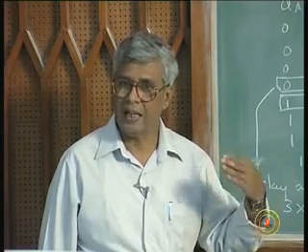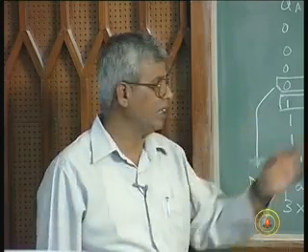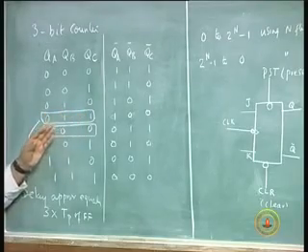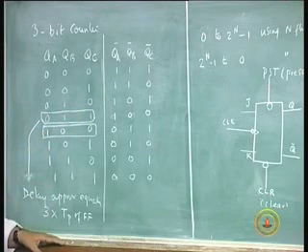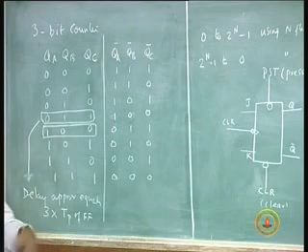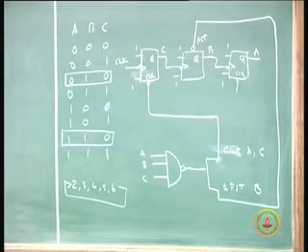So there is a delay in each flip-flop stage which affects the change. And the more flip-flops there are, the delay in counting becomes longer and longer, right? So if you have 8 flip-flops and 8 stages, with 8 flip-flops what count can I reach?